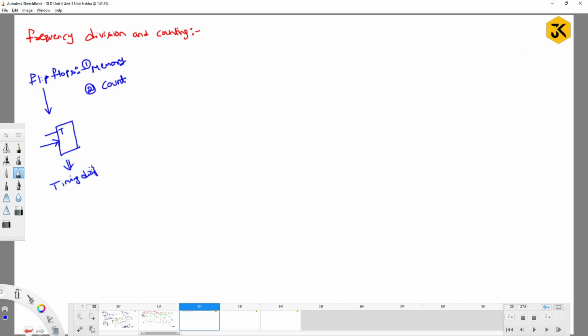When you write the timing diagram, you can observe various clock pulses and how they behave based on the inputs you change. If you take a T flip-flop and give the value 0, the next state will be the present state, that is latch mode. If you give the value 1, it is going to be toggle state, right? This is what you know.